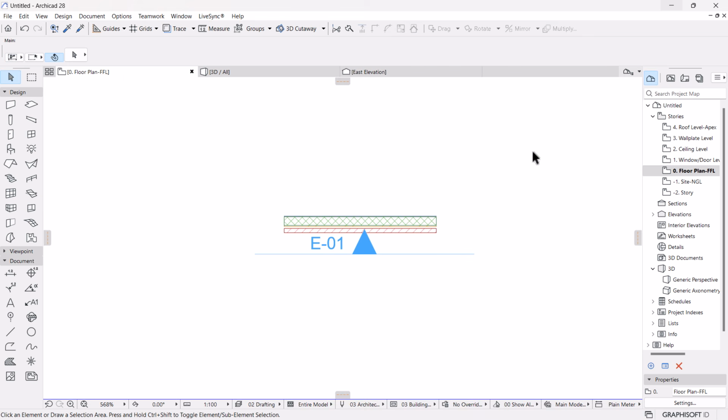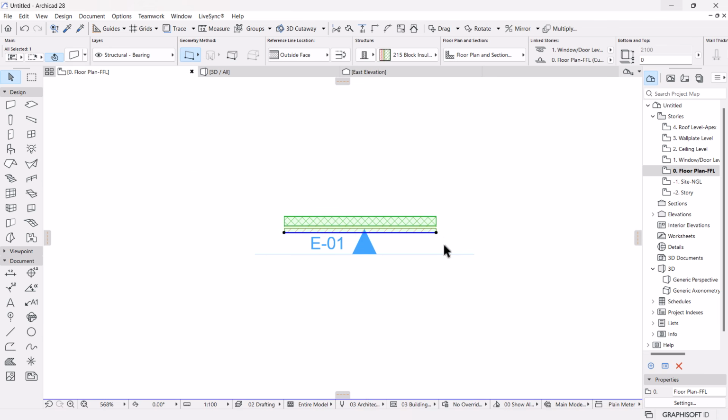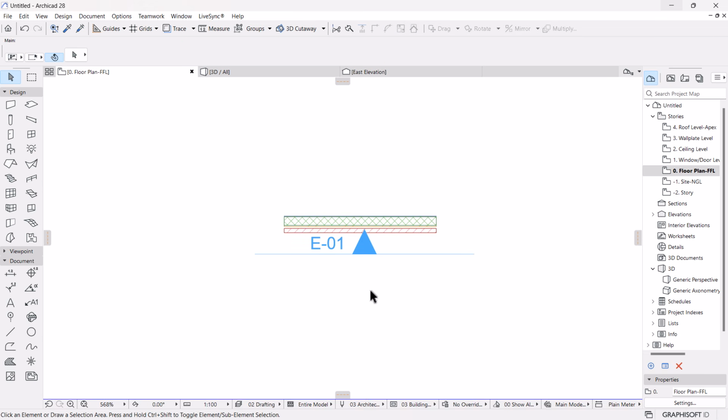And then if you're coming from the right going to the left, it gives you the first method, which is direct selection, whereby you need just to cut across one element, or two elements, and it will be selected, while for left to right, you have to enclose the element. So that's basically different types of selection.